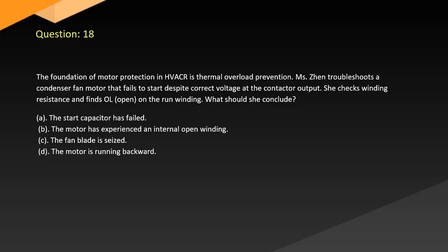Question 18. The foundation of motor protection in HVACR is thermal overload prevention. Technician Zhen troubleshoots a condenser fan motor that fails to start despite correct voltage at the contactor output. She checks winding resistance and finds an open reading on the run winding. What should she conclude?